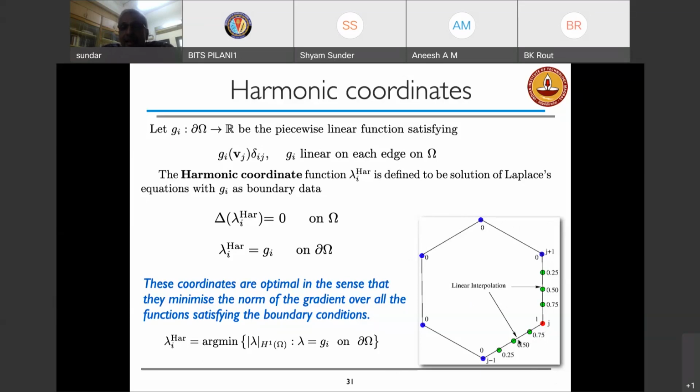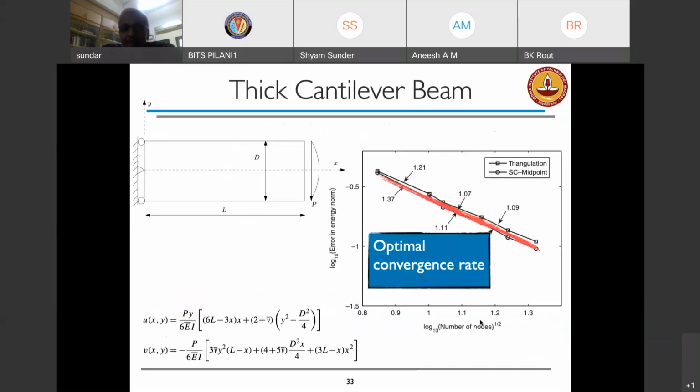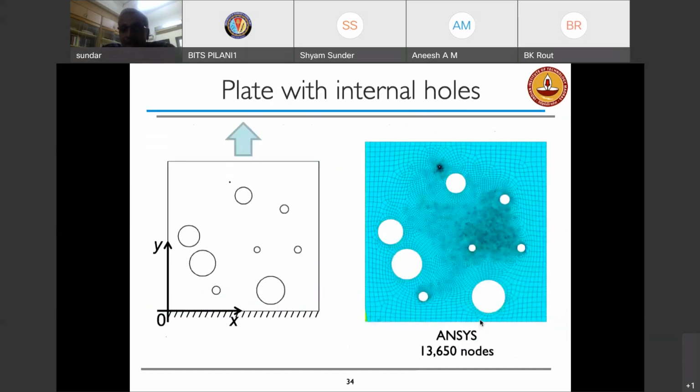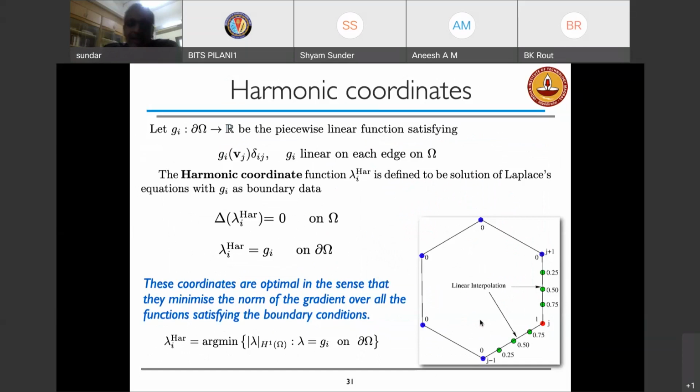This can interestingly be obtained by solving a Laplace equation with the same boundary condition, right? And of course, you may ask, then this becomes a finite element problem. Yes, that becomes a finite element problem. But once you have this library written, you save it in a function. You can now treat this as one big element as opposed to having many elements within it, which drastically reduces the computational effort. This can also be applied in 3 dimensions, which I'll show in a later slide. I thought I had it in the next slide.